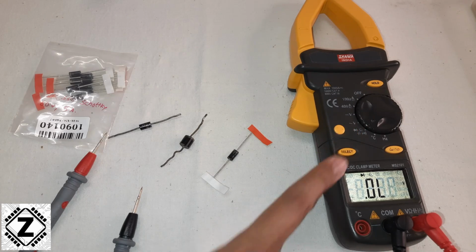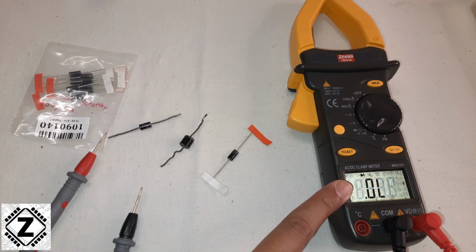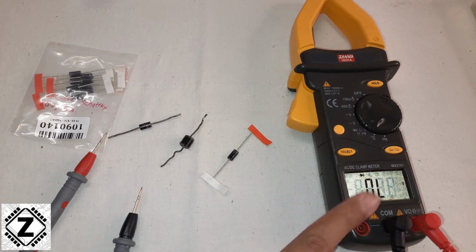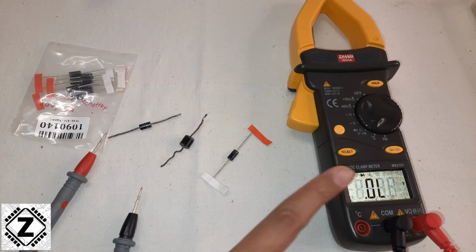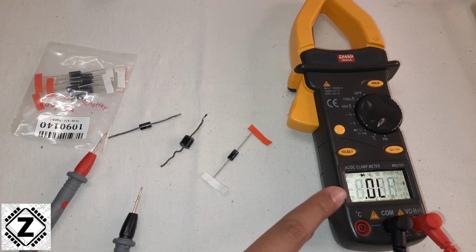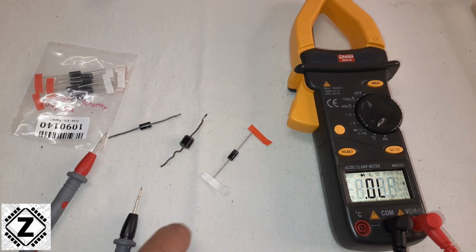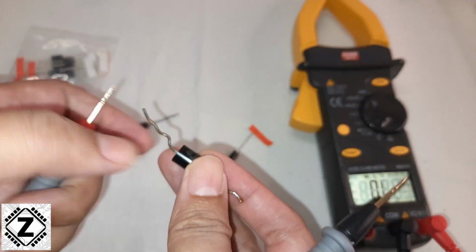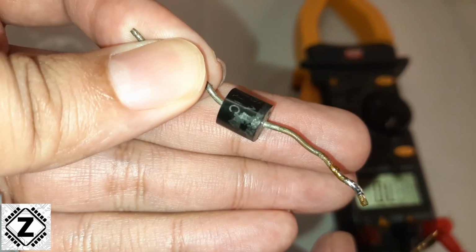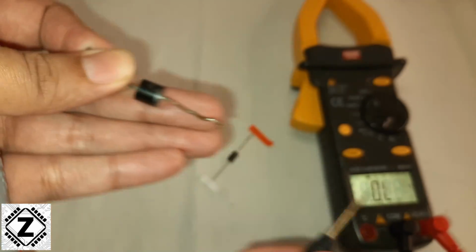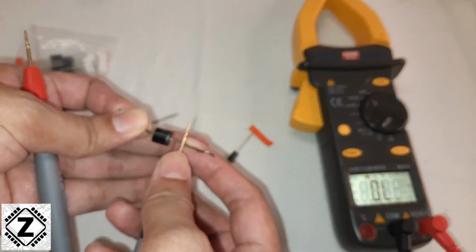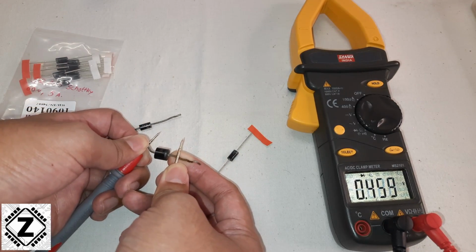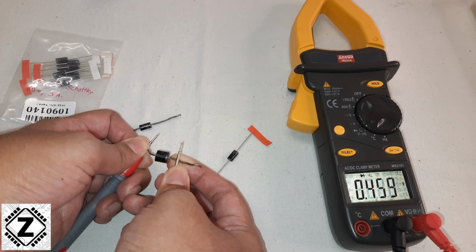This is my Mastec multimeter, bought in 2006. I don't know, it's like 17 years now, and it has been working fine. So yeah, always invest in good quality stuff. And let's start by measuring the electrical properties of these diodes. To measure any kind of diode, remember the silver strip that we talked about? We put the negative probe of the multimeter over there, and the positive probe, we put it like this. And let's focus on the display of our multimeter.